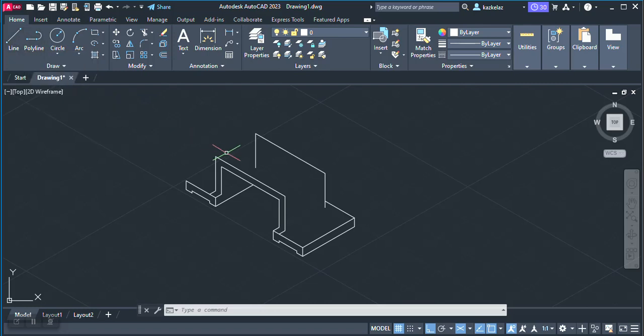So let's start with the ones that we're supposed to put there. I know that I'm supposed to have curves of radius 10. So I'll go and select elliptical arc there on ellipse, right? So I'll select elliptical arc, which is the last one. Then I'll go and select isocircle.